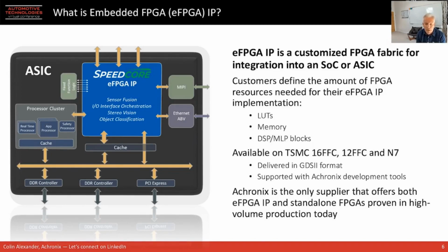The FPGA can be tightly coupled with the CPU subsystem, utilizing off-the-shelf ARM or RISC-V system resources, meaning the eFPGA and subsystem can utilize cache and memory coherency capabilities on the SoC. Unlike standalone FPGAs, designers are not limited to the predefined configurations of the FPGA, and instead are able to make the exact amount of resources required for their application.